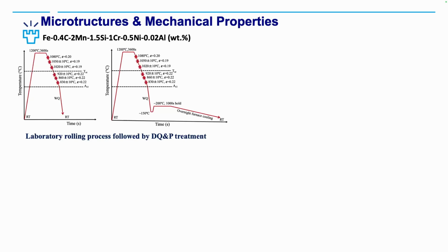Now this silicon is one important alloying element which plays a significant role to avoid this carbide formation. So that's why we played with this silicon content. We have 3 different amounts of silicon, varied from 1.5, 0.75, and 0.25. And then we have chosen another additional alloying element, that is niobium addition. We also wanted to check how this microalloying element plays a role.